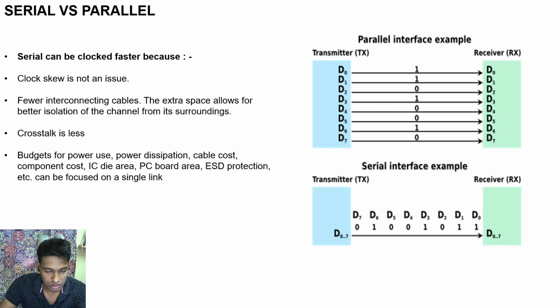So the clock you're sending is not exactly received. And furthermore, you're sending it to two different places. Suppose you have two receivers. Receiver one is receiving one clock, and receiver two is receiving something else. So the difference in clock itself is a problem in parallel communication, because each of these channels will be sampled by a different sampler. Suppose you have eight channels, there will be eight samplers, and if each sampler is getting a different clock, they will be sampling at different times, and ultimately, in a parallel communication, that is a limiting factor.